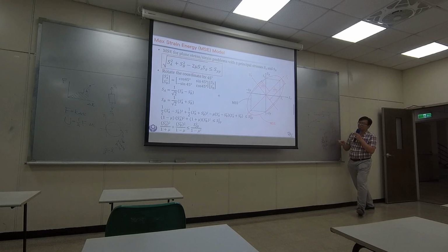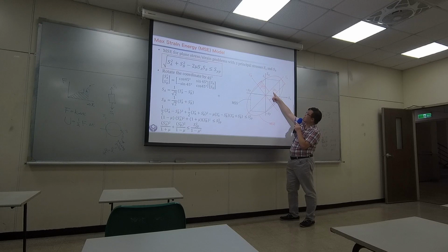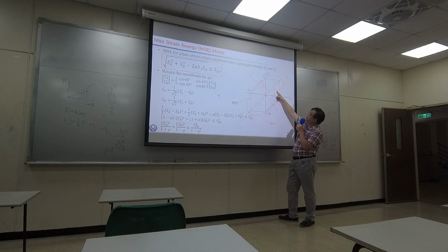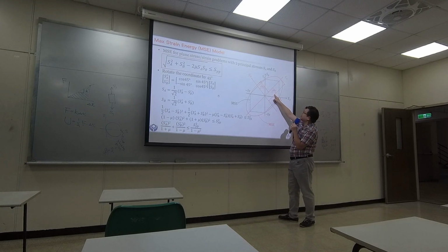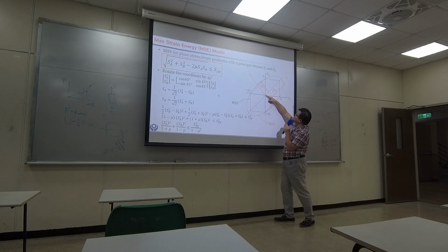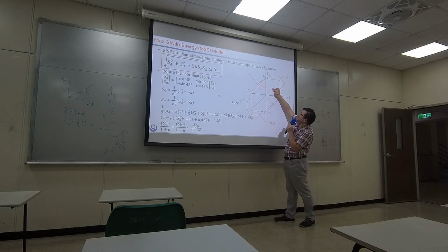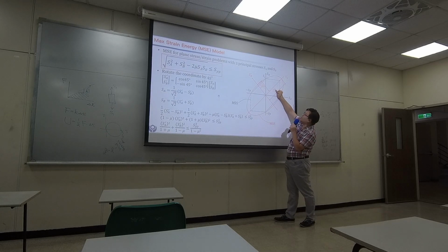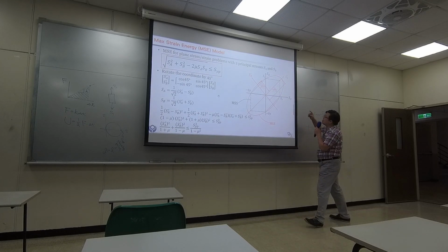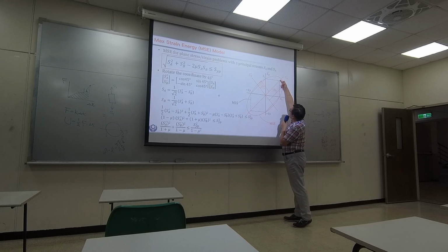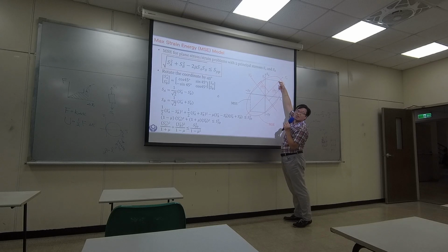And if you try that number here, then you have a square root of 0.5. And basically it's like a half of it, right? And that means this length is gonna be square root of 2 times the yielding strength. So that means when you have Poisson ratio of 0.5, this position is gonna overlap with this upper right corner.